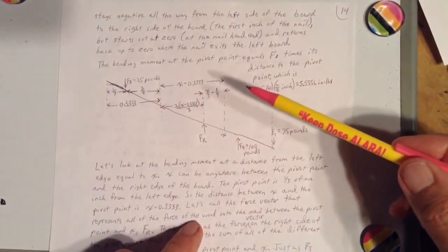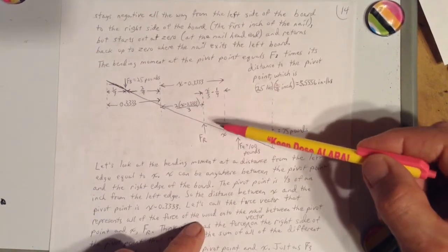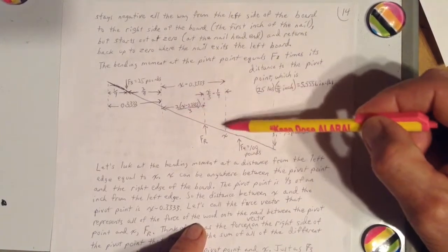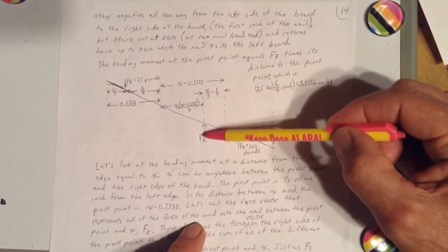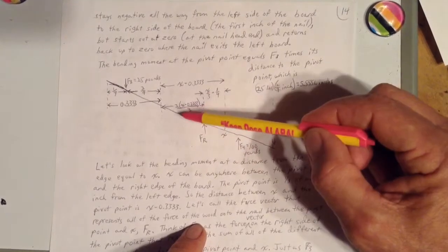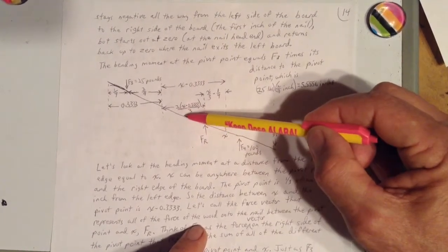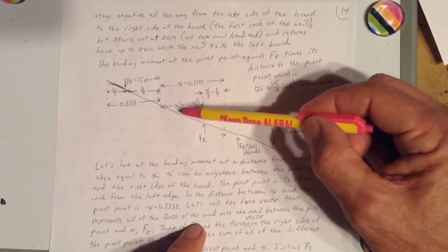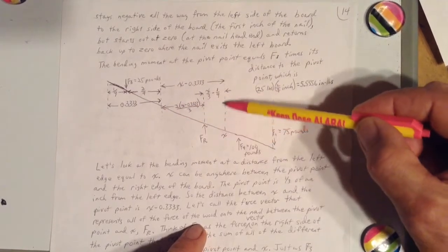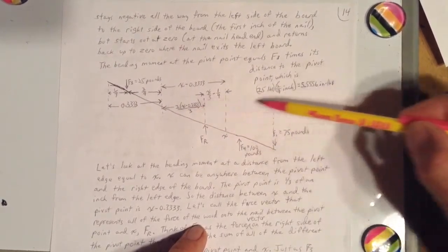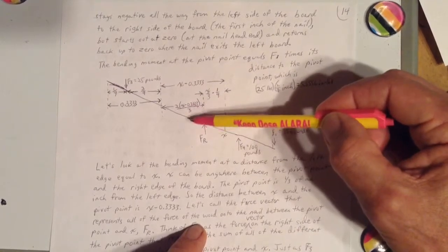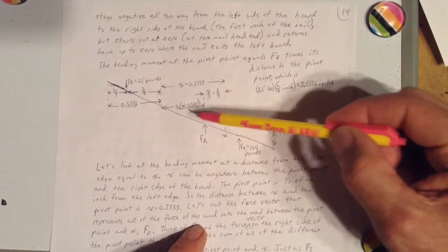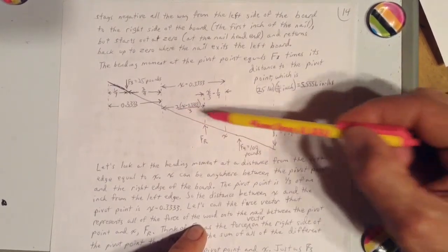Let's call the force vector that represents all the force of the wood onto the nail between the pivot point and point X FR. Like, for instance, if we take a little incremental unit of area between the nail and the wood, multiply it times the stress, which is 0 at the pivot point. It's much more here because this line gets further and further away from the horizontal. We'll have our little incremental force vectors, and FR represents all of them between the pivot point and X.